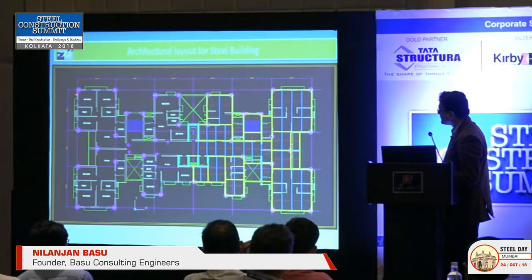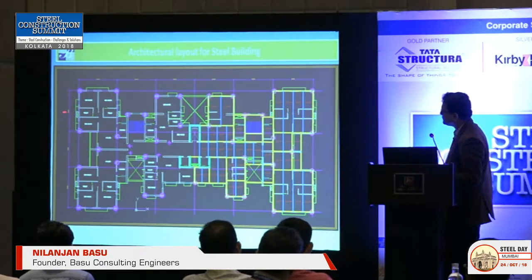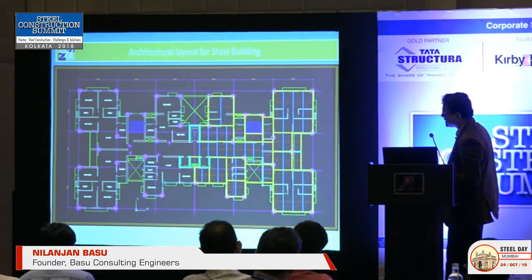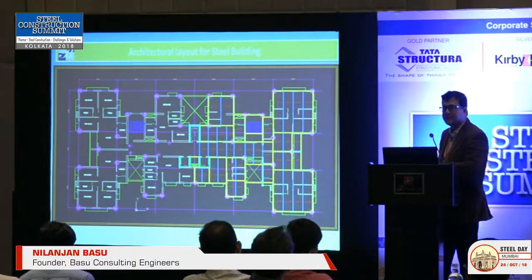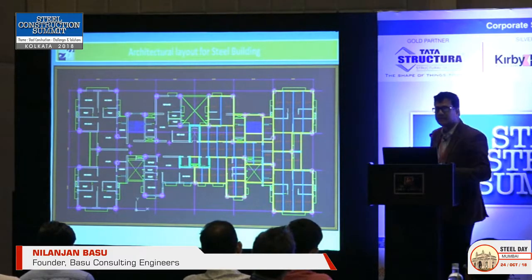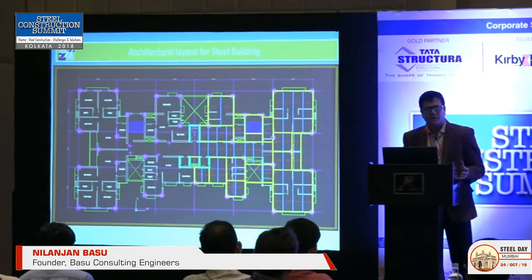And I've placed the column layouts over here so that you can have a look at how the spacings are going. This is an 8-meter span, and this, of course, goes out to 8.5, 9 meters, 8 again, and then 8.5, 9. And on the right side, I sat with the architect and showed him how I would frame a beam layout based on his architecture. If that's acceptable to the architect, we'd go ahead with that.